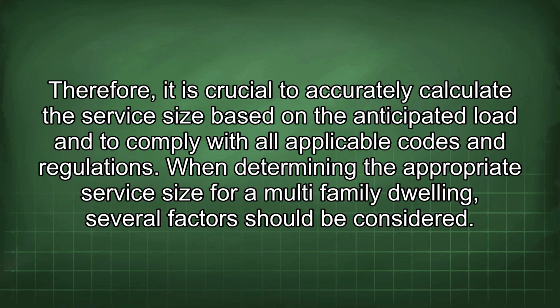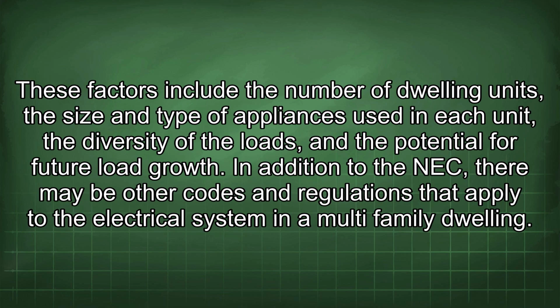When determining the appropriate service size for a multi-family dwelling, several factors should be considered. These factors include the number of dwelling units, the size and type of appliances used in each unit, the diversity of the loads, and the potential for future load growth.